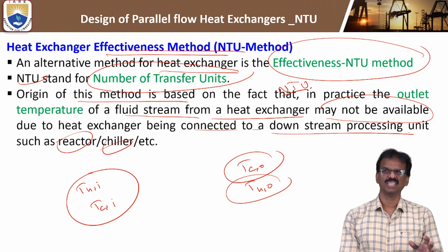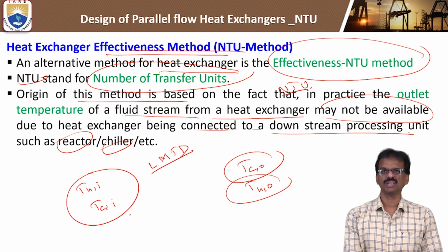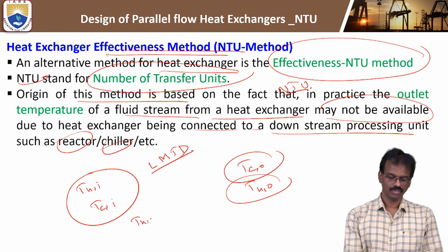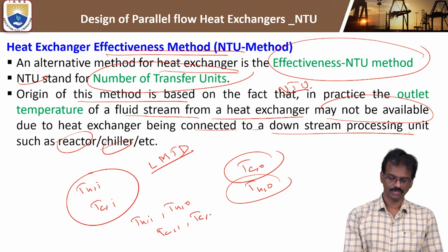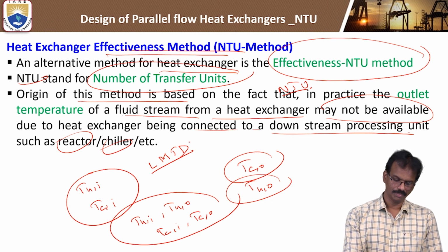For the design of a heat exchanger by the LMTD method, we require four temperatures: the inlet and outlet temperatures of the fluids. That means hot fluid inlet and outlet, and cold fluid inlet and outlet. Then we can design the heat exchanger by the LMTD method.